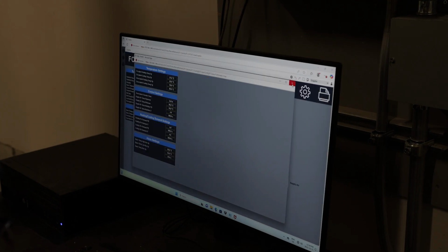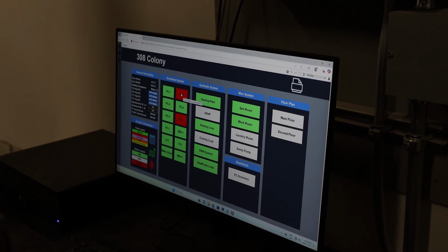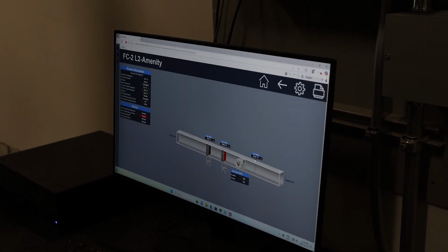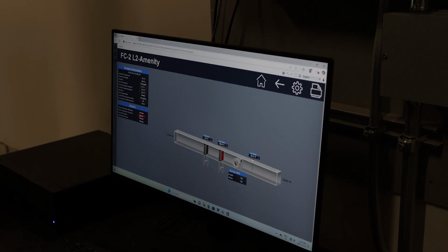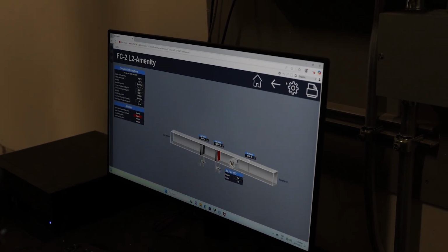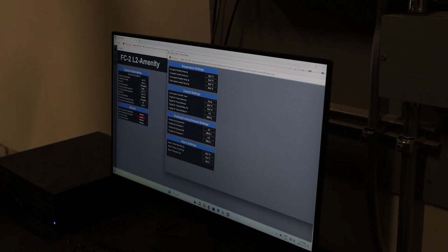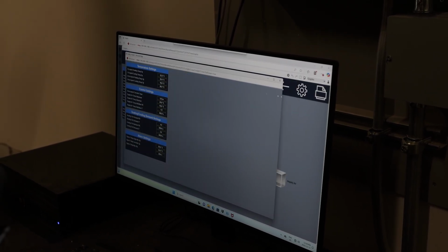The perfect example would be this one. Right now the background is showing red. That means there's an alarm for fan coil 4. If I click the unit, I see a space load alarm. Why is that? Space temperature is only reading 11 C, but our alarm set point is 15. That's why the space is too low and we see the alarm.